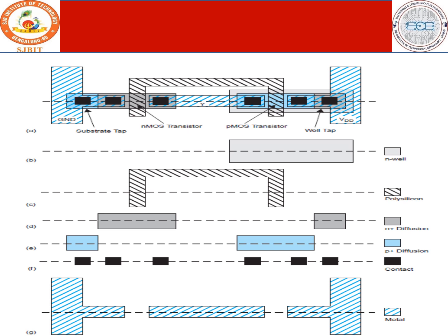Now we have different types of masking. Now you just check what this is. This is your polysilicon and this is your diffusion. Therefore, transistors are being formed here: PMOS transistor and NMOS transistor. Therefore, this is a well structure being created here. This is your ground and this is your supply. So this is the fabrication model which shows the transistor view from the top. If you see, this is how it looks. So this is your NMOS transistor.